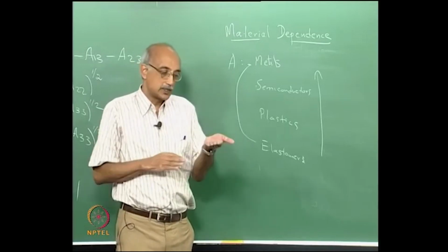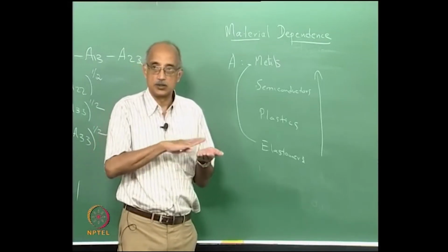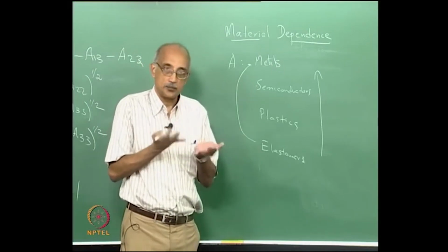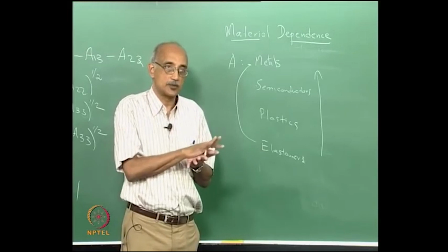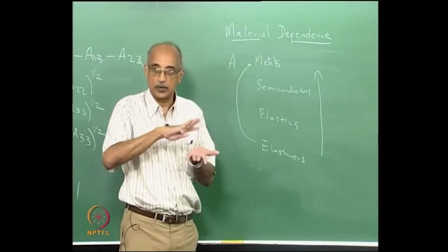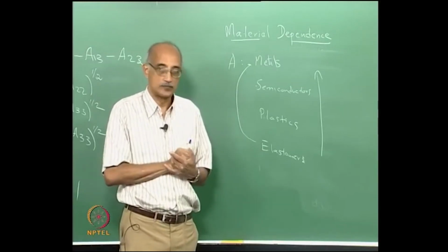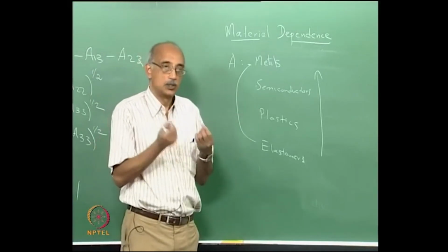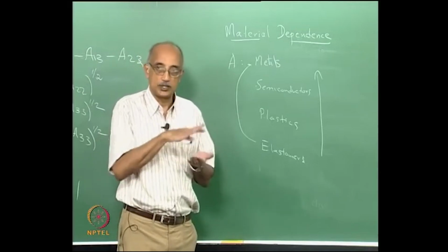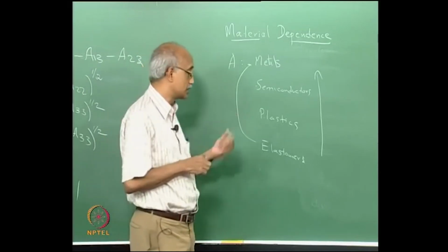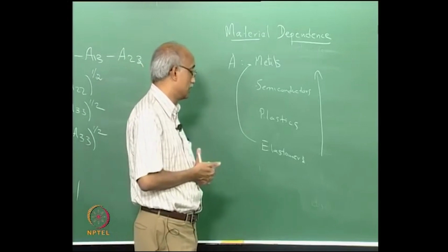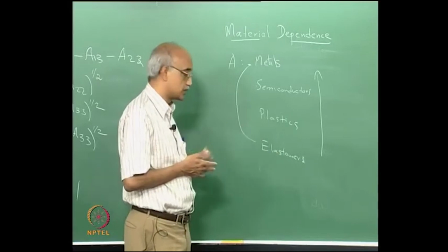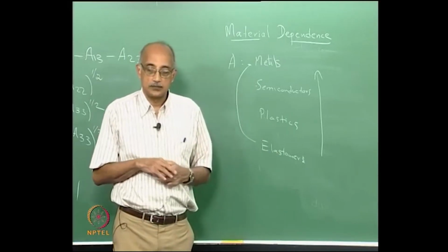However, if you are taking a silicon surface and you want to polish it using silicon oxide abrasive, that is not so good, because there is going to be a repulsion. So the silicon oxide particles may find it difficult to make contact and provide good polishing for the silicon surface. So you may need to use again additives to improve the contact between the polishing abrasive and the surface that you are trying to polish. So there are a lot of interesting implications of this type of behavior that we need to be aware of.